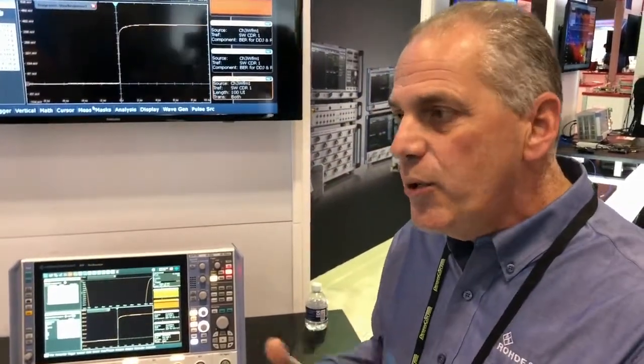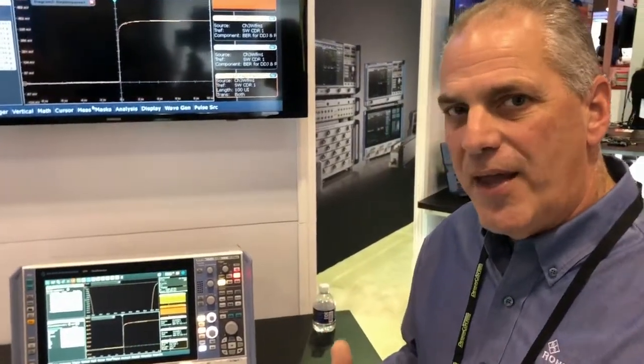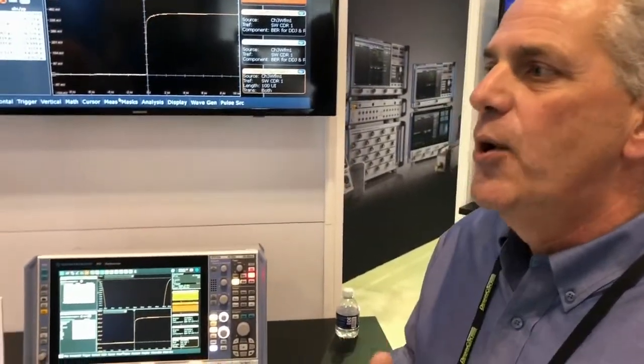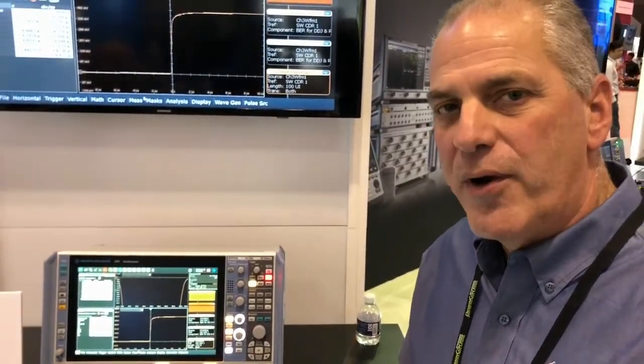Another form of jitter is called random jitter. Random jitter is usually noise related. Not a whole lot you can do about it. Typically just build low noise oscillators and that takes care of it. So what we've done is we've designed a jitter measurement software that allows one to understand those waveform related jitter sources and understand better where they're coming from.